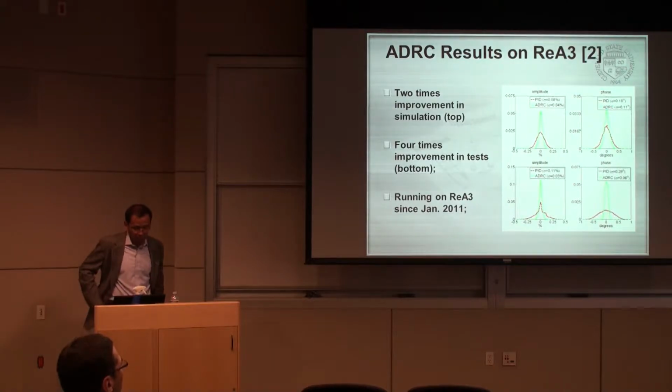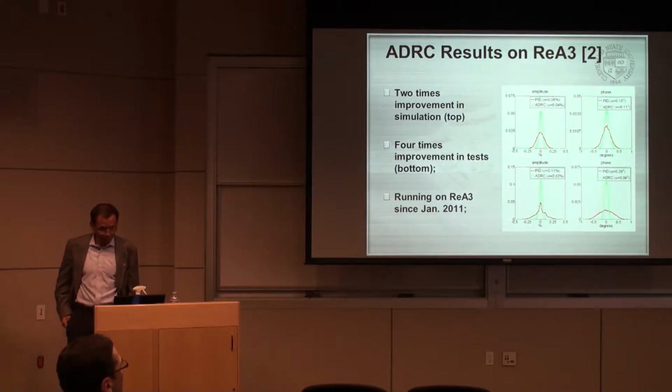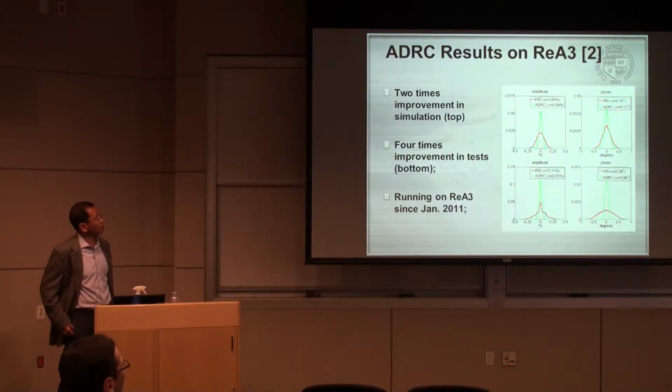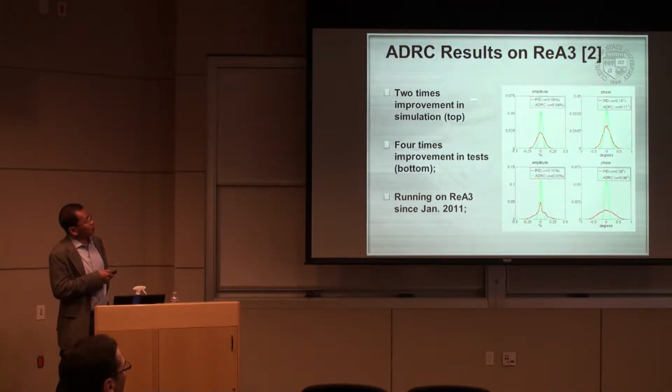We implemented the ADRC in their FPGA, and in simulation, this is interesting, we only see 2 times improvement, that's 200%. But in hardware test, we see 400%. And it's been running since January 2011, over 2 years now.